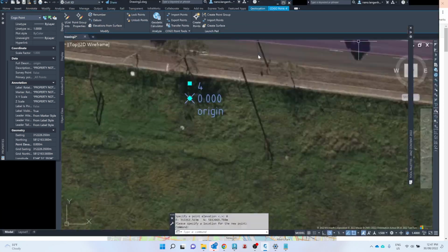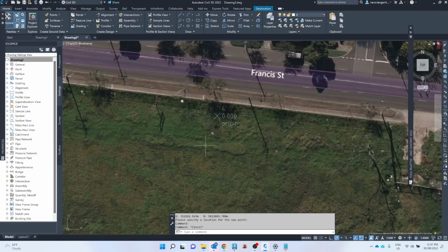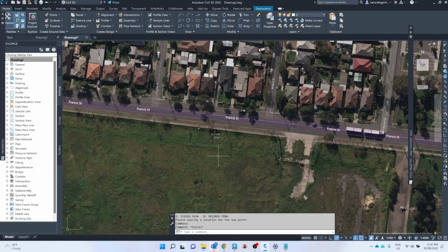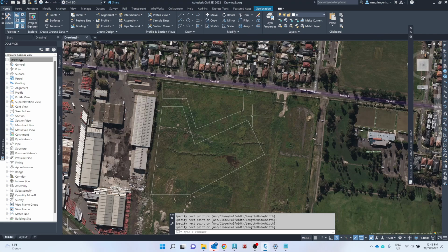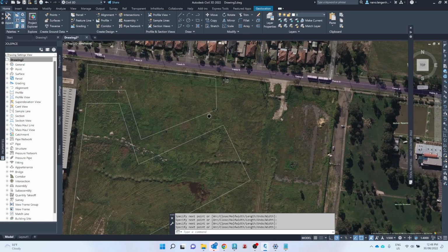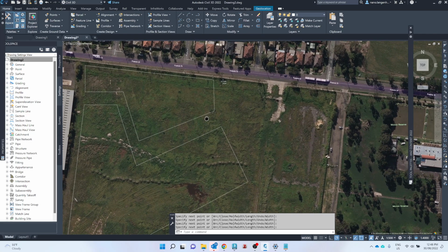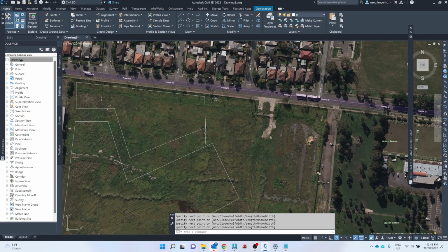And then you will want to get your geometry into this file. So I'll just put some geometry in. So this geometry is what I will export to my 3ds Max file. Okay, so a thing I have to do here is go from the coordinate system that's been set in the drawing into a user coordinate system.